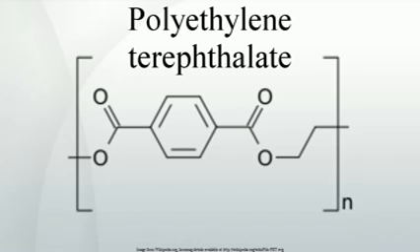Depending on composition and impurity level of the input material, the following general process steps are applied: bale opening, briquette opening, sorting and selection for different colors and foreign polymers, especially PVC, removal of foreign matter such as film, paper, glass, sand, soil, stones, and metals, pre-washing without cutting, coarse cutting dry or combined with pre-washing, removal of stones, glass, and metal, air sifting to remove film, paper, and labels, grinding, dry or wet, removal of low-density polymers, cups, by density differences, hot wash, caustic wash, and surface etching, maintaining intrinsic viscosity and decontamination, rinsing, clean water rinsing, drying, air sifting of flakes, automatic flake sorting, water circuit and water treatment technology, flake quality control.